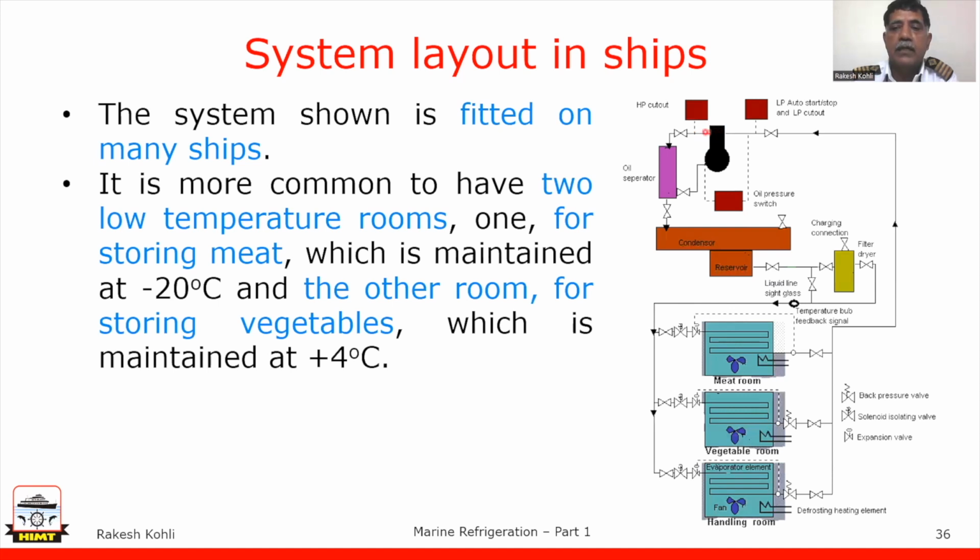And then on the other side we have another safety on the high pressure side, which is the high pressure cutout: if the pressure goes high, the compressor gets switched off. All these are electrically connected to the panel.